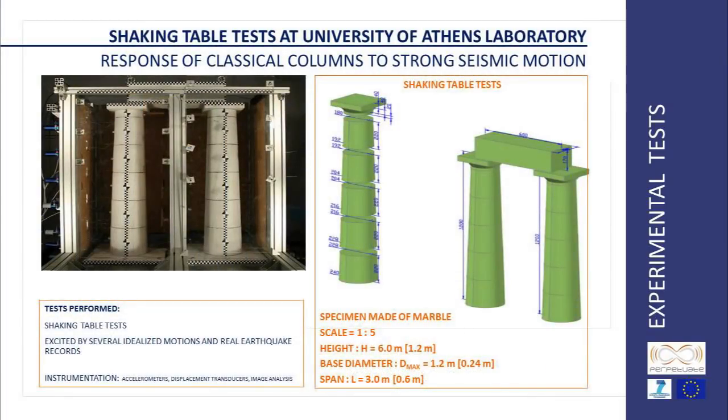In particular, a series of experiments on the shaking table of the Soil Mechanics Laboratory of the National Technical University of Athens has been conducted to investigate the dynamic response of single or two connected multi-drum columns, namely a portal. A database of results from a total of 125 tests was developed as the specimen was excited by a large set of idealized pulses, as well as real records from various earthquakes around the world.